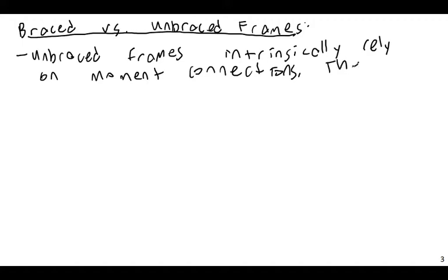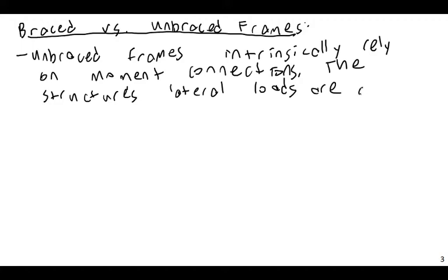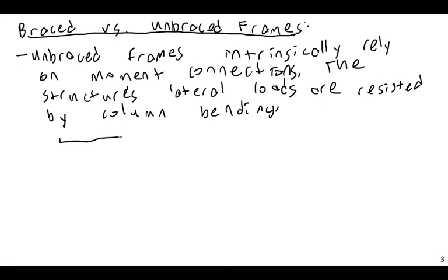The lateral loads of the structure are resisted by column bending. And as such, the connections need to be able to transmit this moment, any moment that is present. So if you have a building that is undergoing a lateral loading,